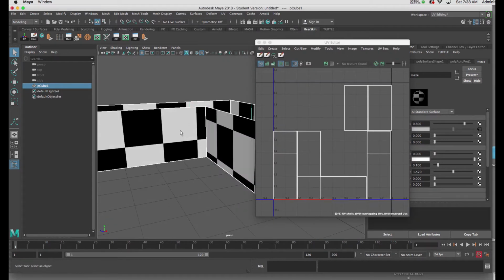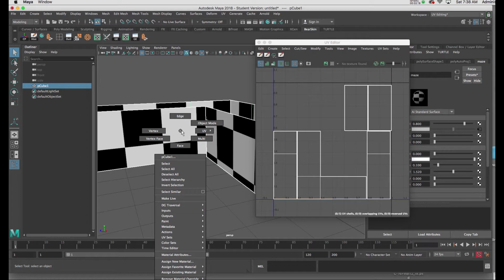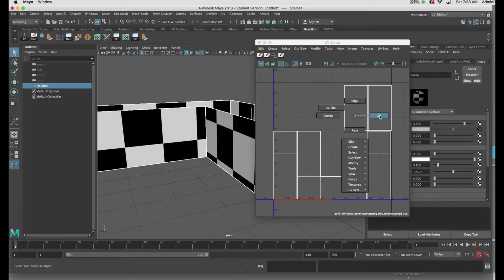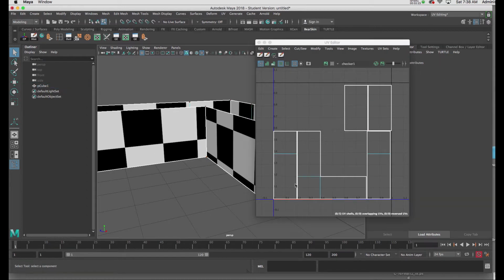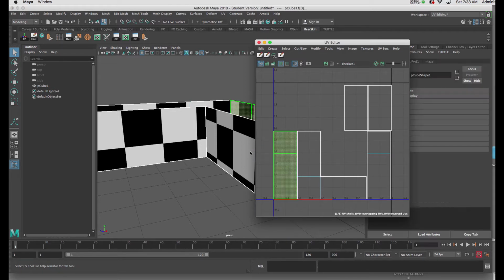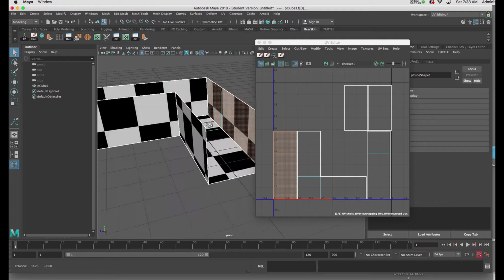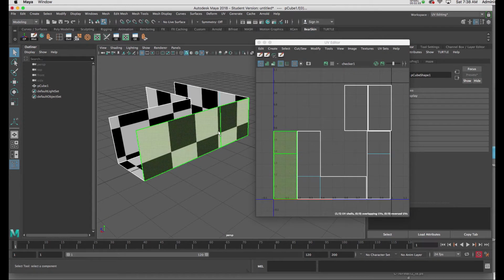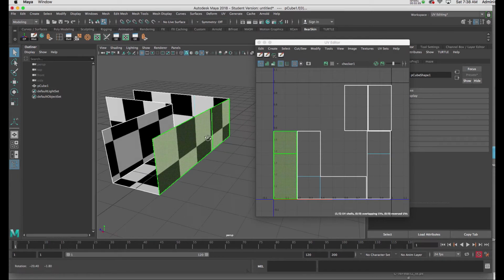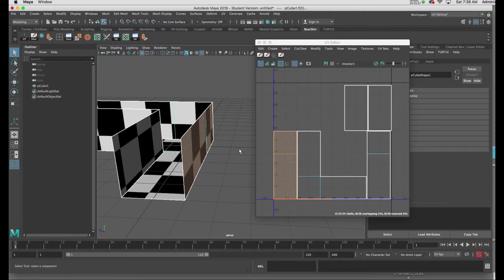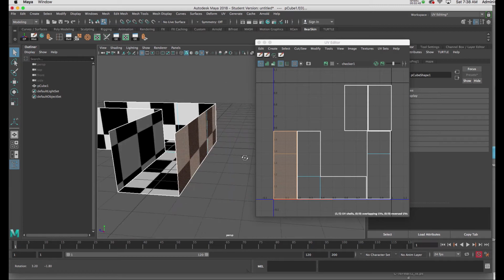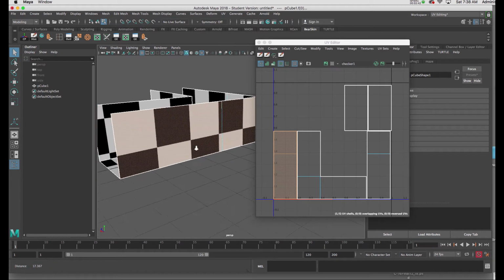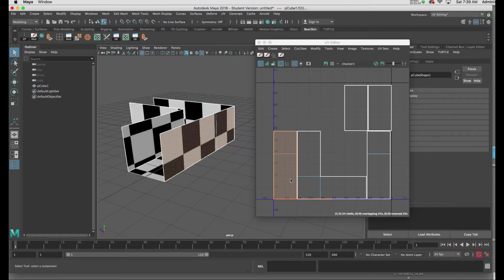Now we're going to go in and select the UV maps for each of the walls. When we do that, under UV shell, we can select them and look at our model and we can see the reference inside our viewport. So my objective is to put all of the UV maps representing the walls of this maze on top of each other so I can minimize the amount of texturing that I need to do.